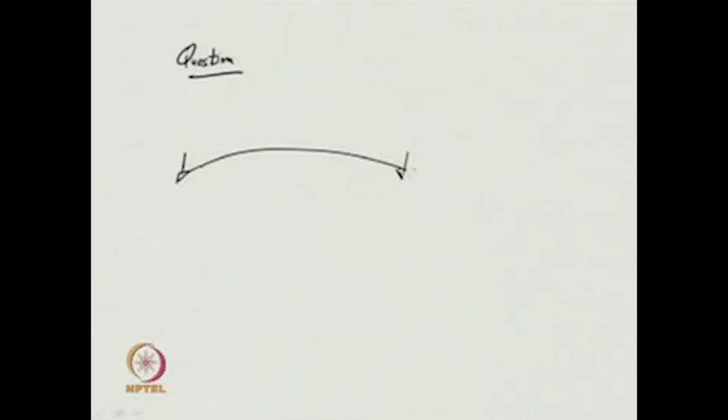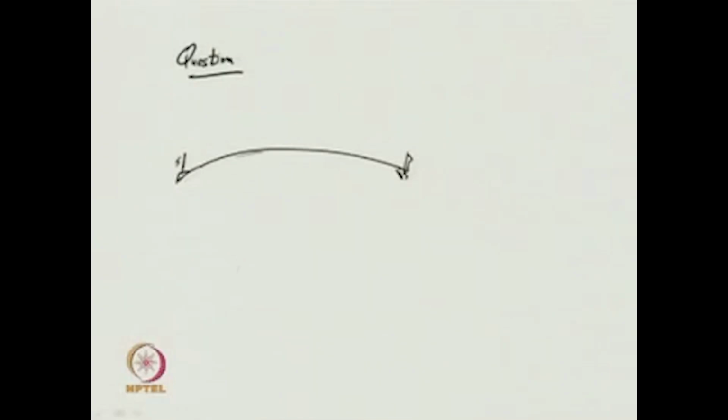Now, you can use your uniform flow approximations to compute flow along these gutters, that is also quite possible. You can also use your overland flow approximations along these portions to find the discharge or discharge per unit width, and then arrive at the discharge quantity here, then subsequently incorporate uniform flow along this main triangular gutter channel. If I just show it in an elaborated way, it may look like this, something like this. So, this is your triangular main channel, water may be there.